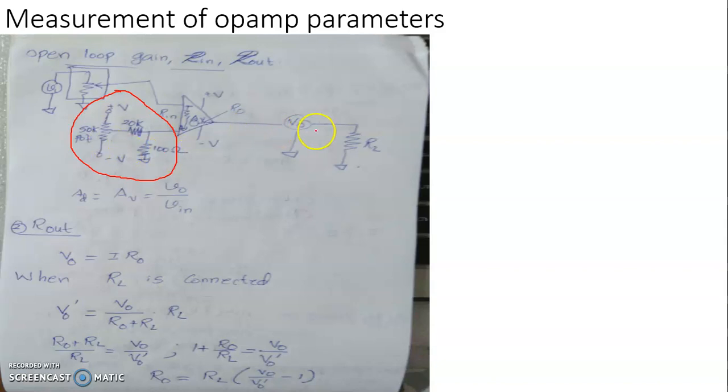So if there is such an output, what we have to do is move the wiper of the pot meter until the output voltage becomes 0. Once it happens, we assume that the input offset voltage is balanced by the differential balancing voltage that we have supplied.